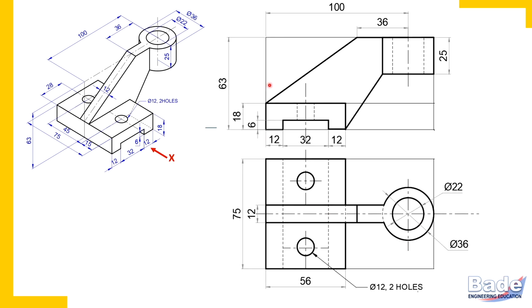And then insert dimensions. You are asked to insert 6 dimensions. I have inserted here all given dimensions. Remember, nearest dimension line must be at least 6 millimeters away from the boundary. This is parallel dimensioning, 2 parallel dimension lines at least 6 millimeters away from each other. Then here, these are take care of all details of dimensioning.